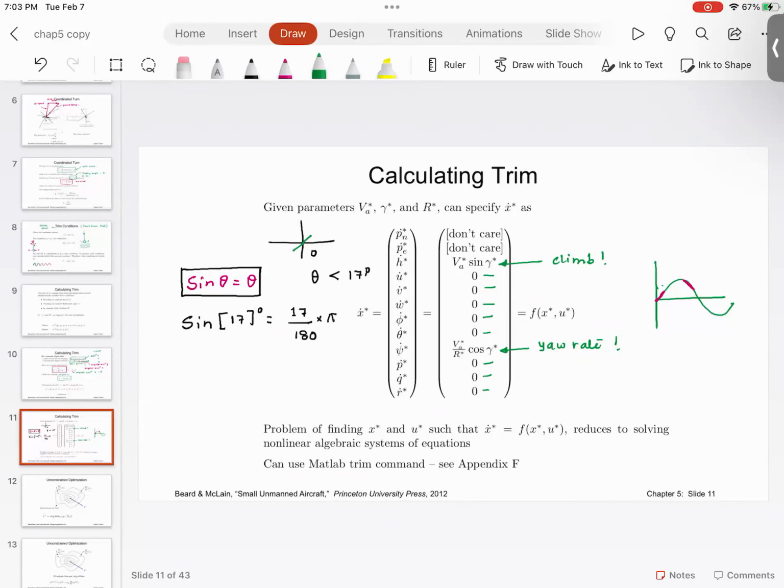It means if you have this complicated nonlinear equation or nonlinear dynamical system, and you want to understand whether that system is stable or unstable, then what you do is you find the operating point, you find the linearization, and find the eigenvalues of the linearized system. Remember, nonlinear systems do not have eigenvalues.